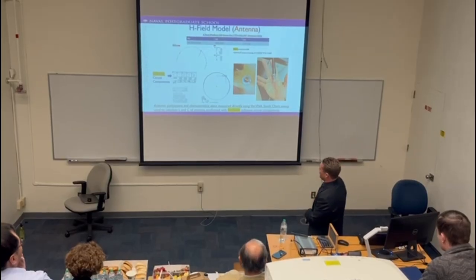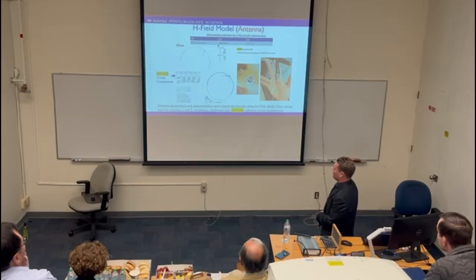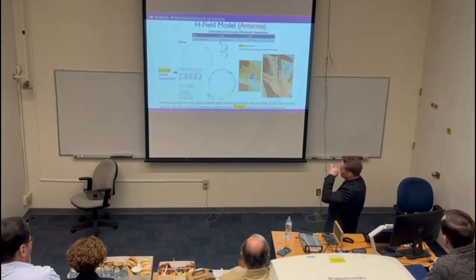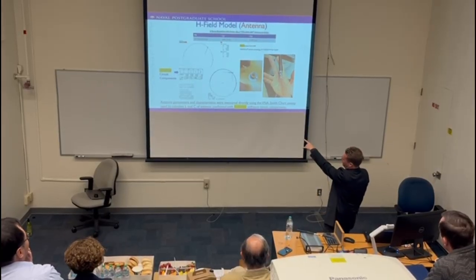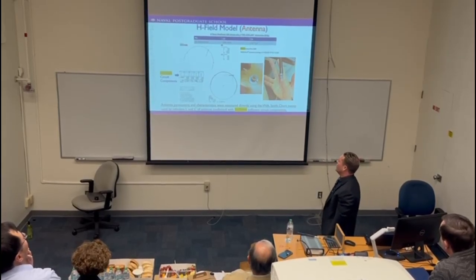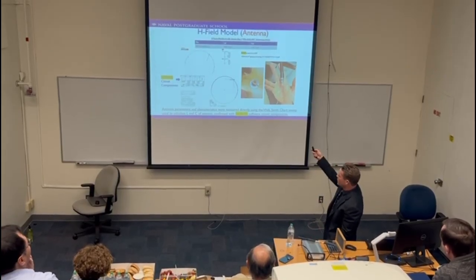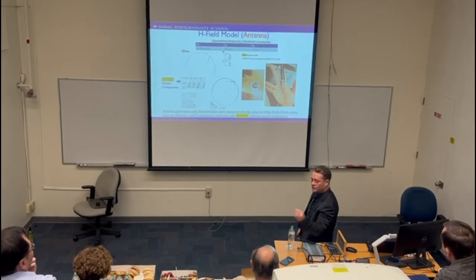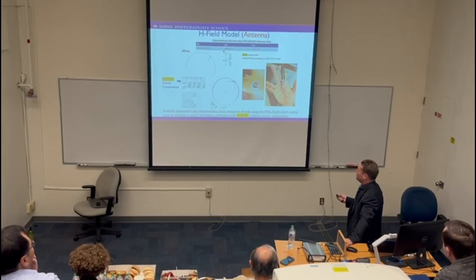Again, this is my VNA here, and I used a program named SimSmith. That is really cool. I can literally overlap a trace on a Smith chart, looking at its impedance across my frequency range, and overlap it with a mapped out circuit equivalent of what that should be. And so that helped a lot. I was just comparing and contrasting everything as accurately as I could with what the inductance and capacitance were. Obviously, if I have multiple turns, I'm going to have a bit of capacitance between the turns. But the capacitance was always relatively negligible, very small.